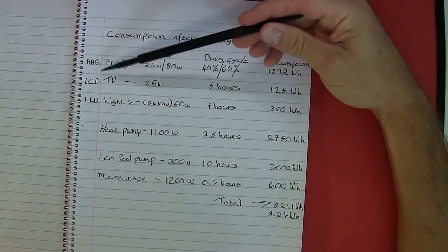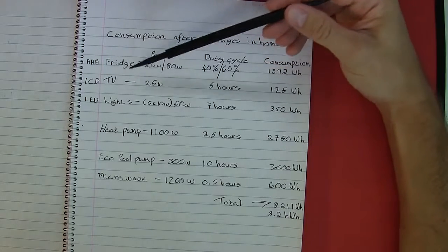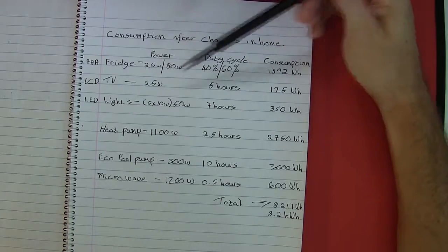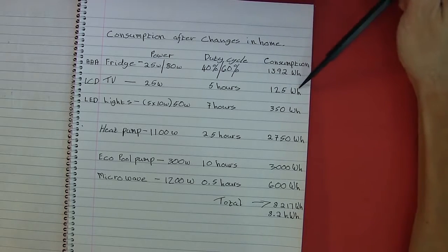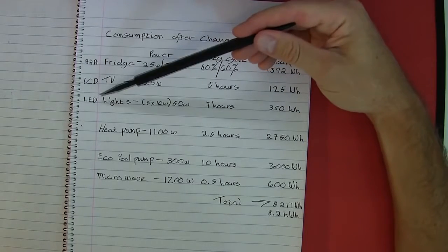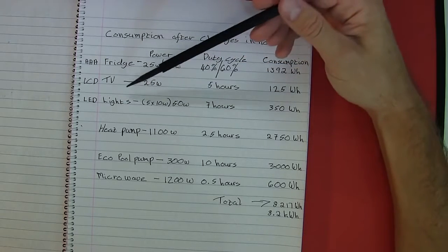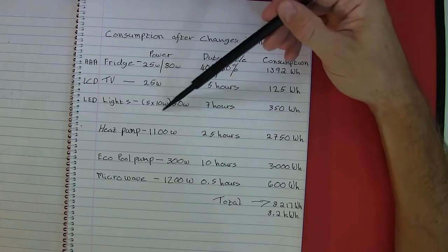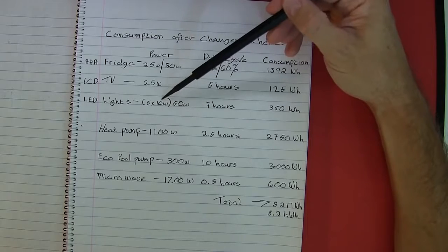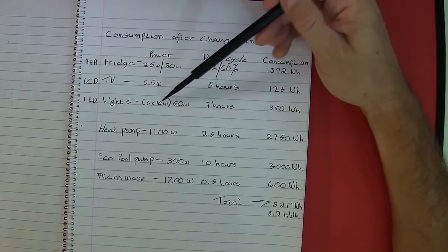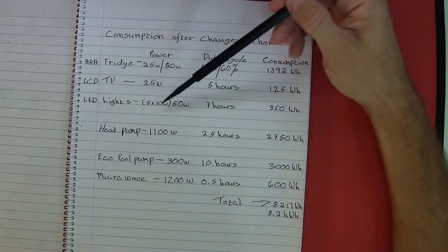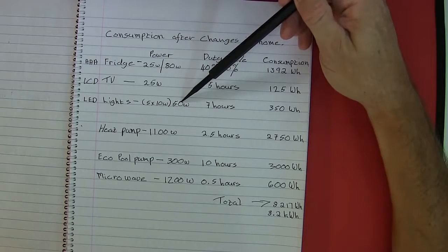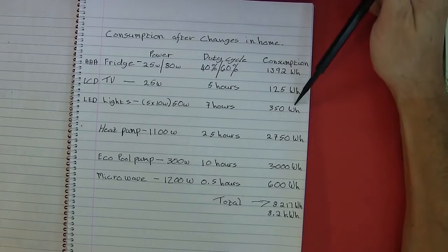A TV, if you go to these new modern LCD TVs, for an equivalent size TV, you could drop from 80 watts down to, let's say, 25 watts. And that would then bring you down to 125 watt hours. If we change those downlighters from the 50 watt downlighters to, let's say, 10 watt downlighters, now I'm being quite generous here because you could drop below that, but let's say you want some good lighting, so you don't want to go to a 5 watt LED, you're going to go 10 watt, still that's a fair saving. You're now going to be using 50 watts as opposed to 250 watts, so that goes to 350 watt hours.